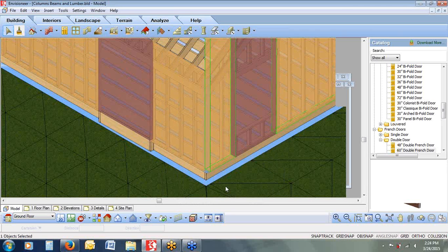Majority of the reasons why you would frame a different wall, well, think of your garage walls where you might want to have a pressure-treated bottom plate. Or perhaps you don't use blocking at all, but there's a kitchen wall where you're going to be legging in some cabinetry. You're going to want some blocking there, so you're going to want to show that in the framing. So instead of following the main rules, those walls can have something different.